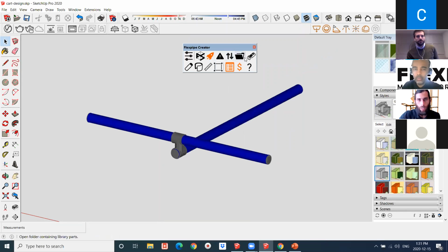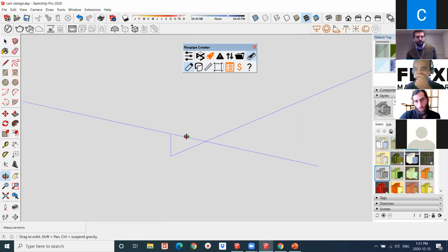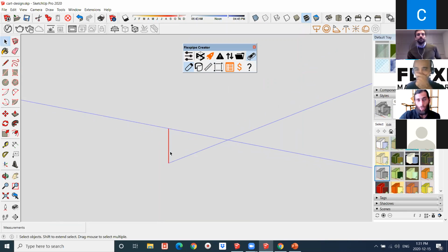So what we did there, if we get rid of the connectors as well as the tubes, we can see that we drew, like I mentioned before, a spacer joint, right? So this is just a small little line. We do have the PDF, which we can provide for everybody. And in this PDF, we give in detail how to draw these particular types of joints, such as the HJ13, the HJ24, and any kind of joint that is going to hold two pipes either parallel or perpendicular to each other. These kinds of joints are going to be using this type of setup here.